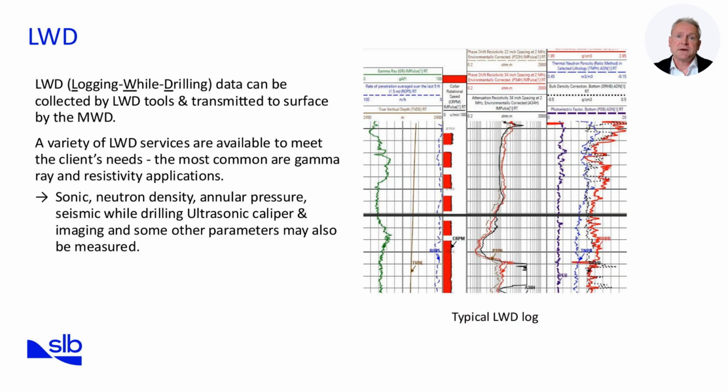Now that we've covered measurement while drilling, MWD, it's time to turn our attention to its equally important counterpart, LWD, which stands for logging while drilling. These tools acquire formation evaluation data while the well is being drilled. LWD tools integrate the sensors directly into the bottom hole assembly, BHA, so they collect data as drilling progresses. This allows for real-time formation evaluation, which means we can make smarter decisions faster, reduce risks, and optimize wellbore placement